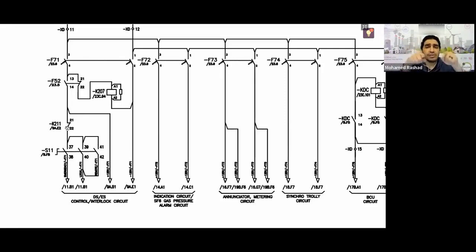At the same time, we used K211 to disconnect the negative in the circuit breaker circuit so that I cannot give a close command to anyone. For the circuit breaker, clear and nice. Okay, someone might ask me, well, why did you disconnect the emergency, local, and remote with it and not the direct DC? I'll tell you, it's very simple.